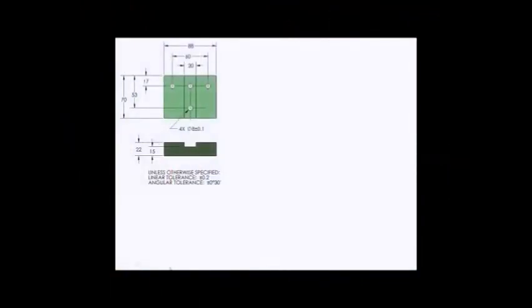I continue to be amazed that there are still drawings out there like the one shown here, where there are no datum features and no geometric tolerances, and people actually think that this general tolerance will do the job. I don't know how to set the part up. I don't know what my origins of measurement are. I have lots of features to choose from. And some people argue, well, I know what they want. And sure, you know what they want.